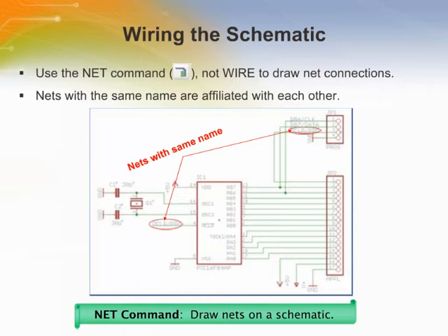The actual route that the line takes is controlled by the wire bend setting for the line, which you can control with your right mouse button. Schematic designers tend to like nice straight lines with right angles. Nets with the same name are connected to one another, regardless of whether or not they appear continuous on the drawing. This is very useful when they appear on different schematic sheets.